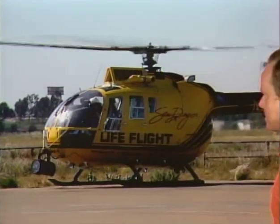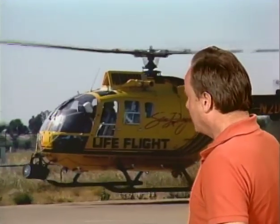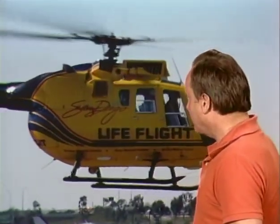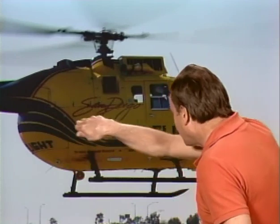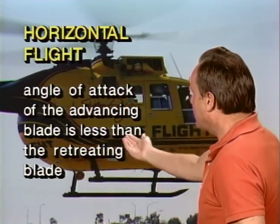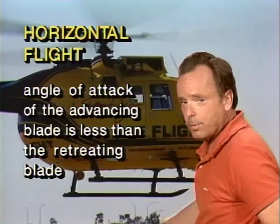Now let's take a look at a few questions the FAA asked you about helicopters. One of the questions they ask is, let's assume you're flying in this helicopter and you manage to get it in straight and level horizontal flight. And I think we're eventually going to get there, maybe, maybe not. They're going to ask you, how does the angle of attack of the advancing blade compare to the angle of attack of the retreating blade? Well, the advancing blade is going faster through the relative wind than the retreating blade, so therefore it has to have a smaller angle of attack. So the angle of attack of the advancing blade is less than the angle of attack of the retreating blade.